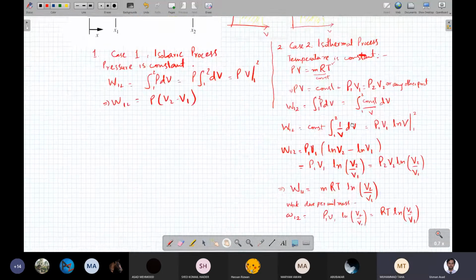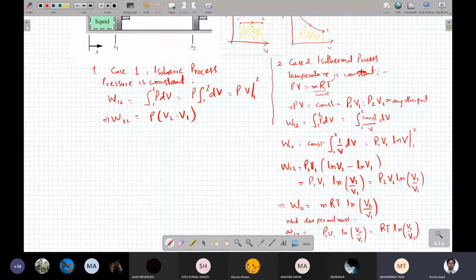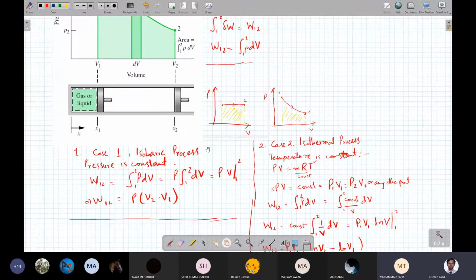Yes, sir. Okay. सुमित. सर ये तो ग्राफ्स बनाए हैं आपने ऊपर, ये पहला आइसोबैरिक का, दूसरा आइसोथर्मल का है सर, इसमें वॉल्यूम प्रेशर पे डिपेंडेंट नहीं होता दूसरे में? Dependent. हाँ तो ठीक है ना, दोनों में there's a relationship between pressure and volume that we are showing, right? So यहाँ पे that relationship is दूसरे वाले में like volume, pressure और temperature पे dependent होता है ना, temperature constant है, तो what we are left with is के P is equal to some constant over V, right?